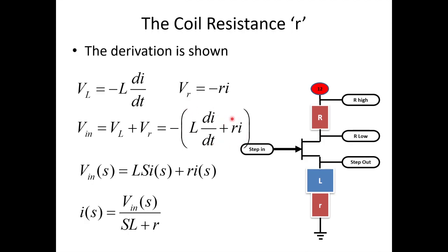And so we're going to transform this into the spectral domain. Okay, constants transfer over no problem. Your functions as a function of time transfer to a function of spectrum. And because this is a derivative of your function of time, you transfer the function as a spectrum and multiply by s to represent that this is the derivative of that spectrum. And your voltage in transfers over from the voltage in as a function of time to the voltage in as a function of spectrum.